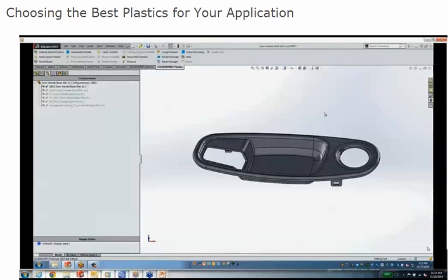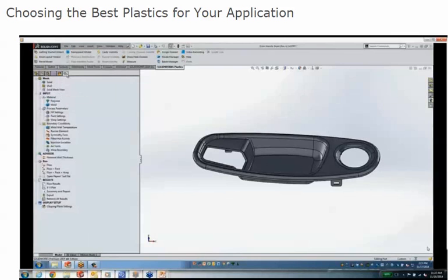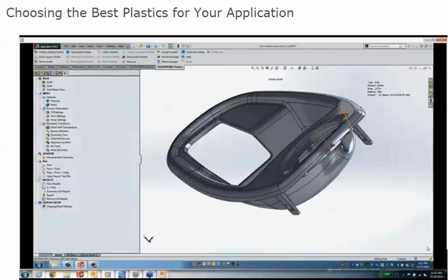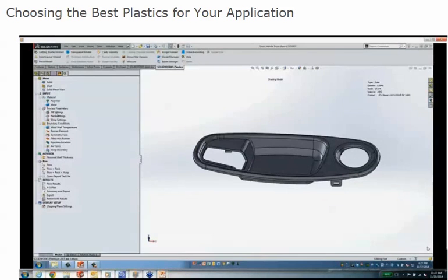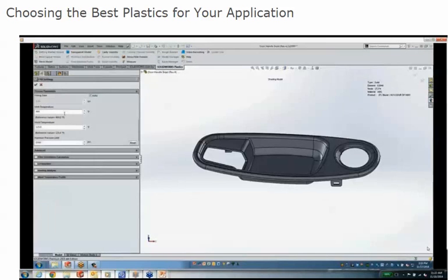So the first thing we may want to do is obviously we're going to choose a material, but next we'll choose an injection location, and we're just going to choose just over here on the side. Next we'll look at some process settings, and what we've determined here is that the injection pressure limit of 8,500 psi is appropriate. We really want to stay below 10,000 psi, so we've added a small safety factor in there just in case there's any other pressure losses further upstream in the system. We want to keep that pressure low, to reduce things like warpage and residual stress in the material after the